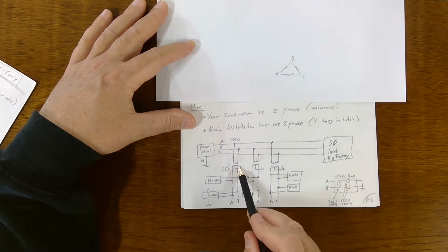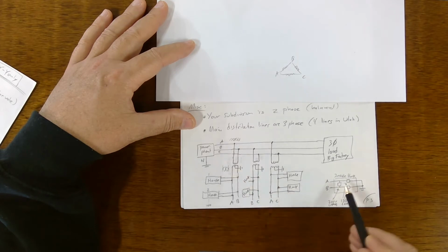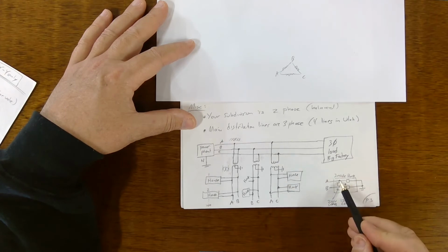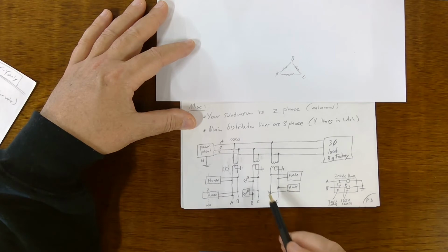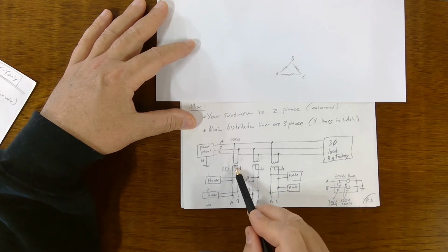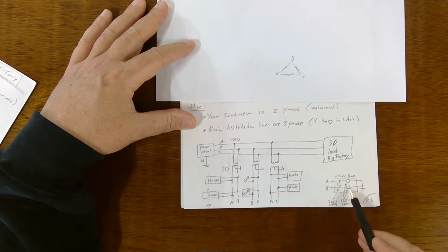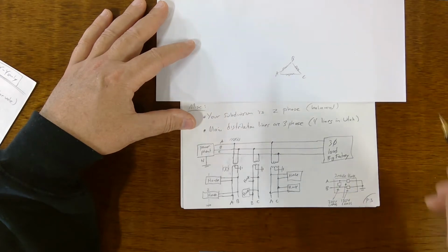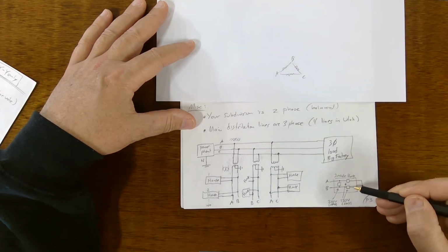If you go across the entire transformer, then you get 220 volt loads that run your anti-asteroid laser and your hot tub. And then you've got peak to center tap, which is grounded, so it's peak to neutral. That's your 120 volt loads, like your toaster and your TV and most of the stuff in your house. By the way, these need to be balanced, right?